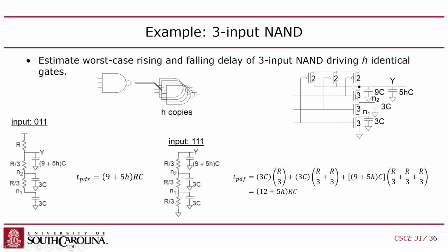And this is with, by the way, notice that the NMOSs are bigger than the PMOSs. This was done deliberately. We want to make these guys stronger because of all the ones that are in series here, right?